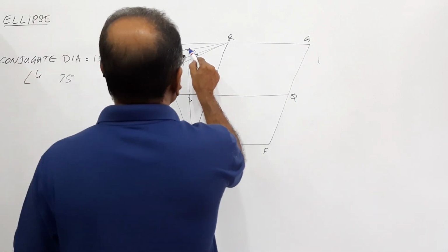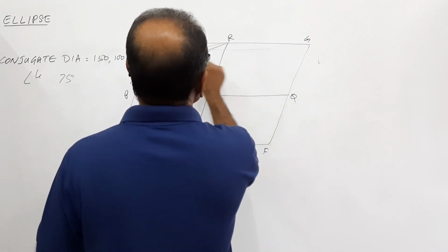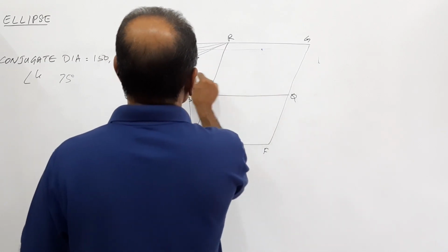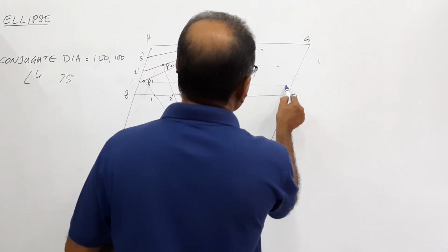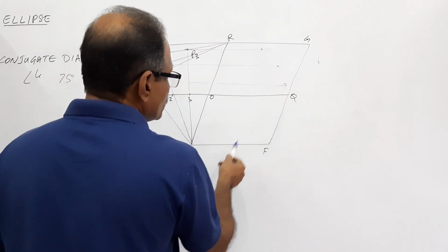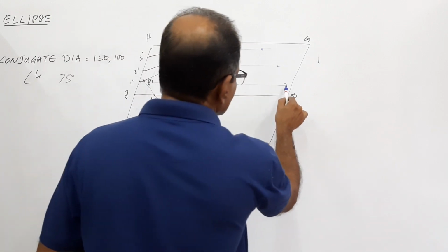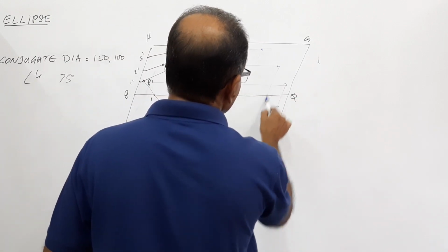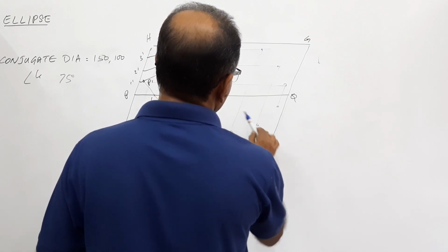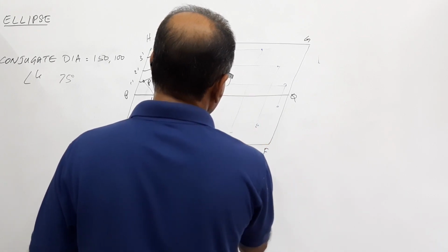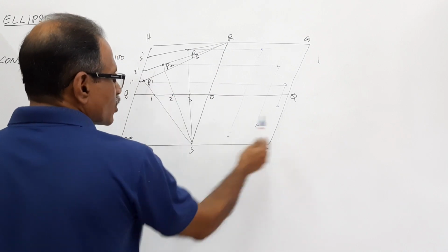Points in the other 3 segments can be either transferred or you can draw the same procedure there. If I transfer, draw a horizontal line through P3, take this distance and mark here. I draw a horizontal line through P2, take this distance and mark here. Do that here also, I get a point there. Come down by drawing lines parallel to this. Agreed? Come down by drawing parallel to that. Now, do that here or come from there.